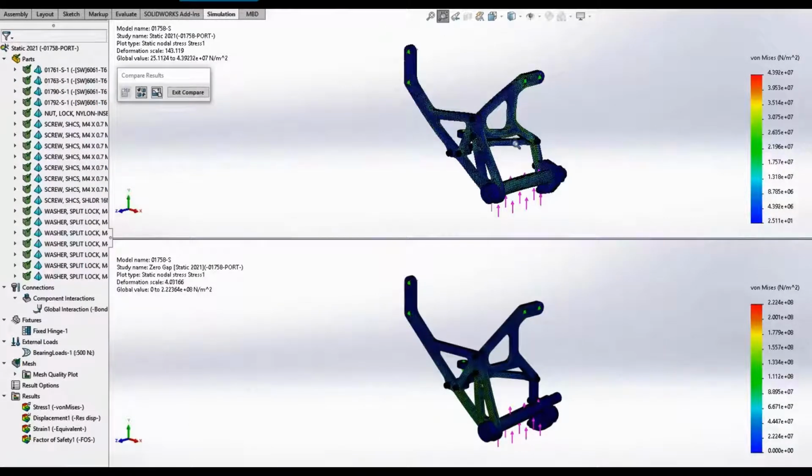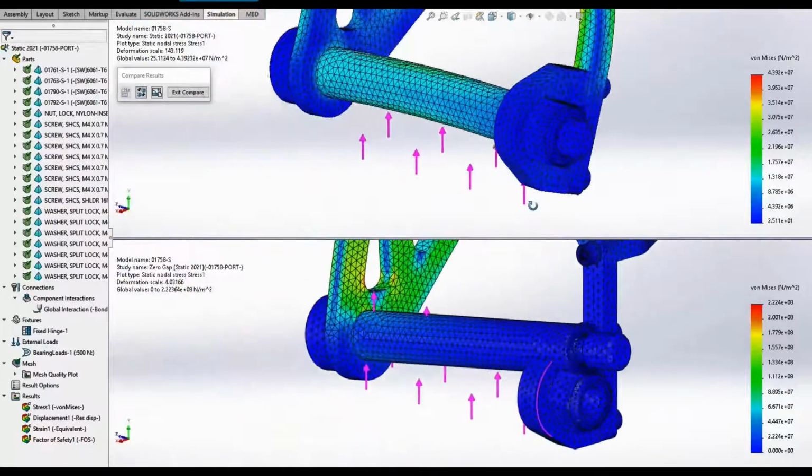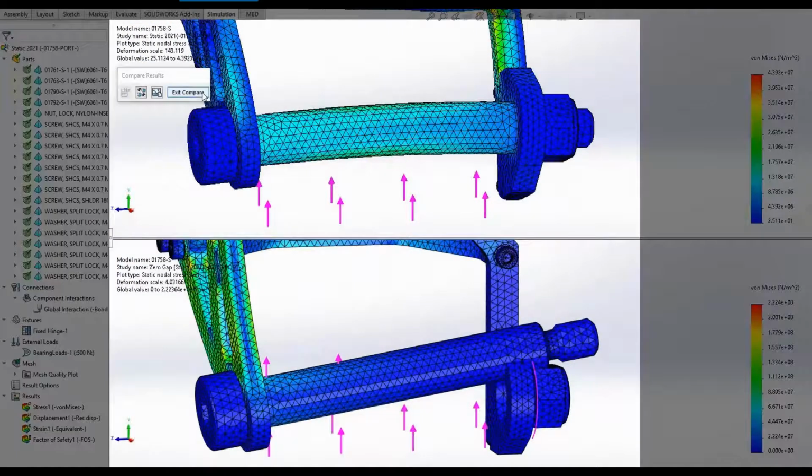I'm sure everyone has probably spent some time inside of SOLIDWORKS Simulation verifying contacts that, if you have a bonded condition, just don't work from time to time. This is much cleaner inside of SOLIDWORKS Simulation 2021 because of the changes that were made. You should be spending a lot less time getting a lot of your contacts to solve using that threshold geometry.